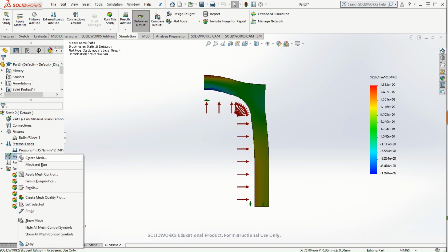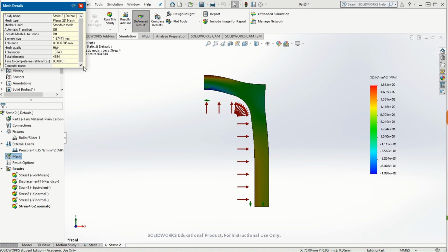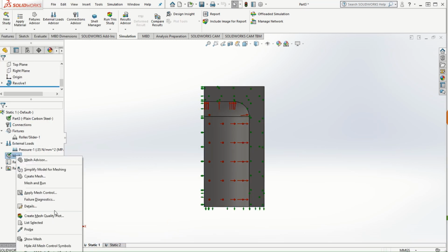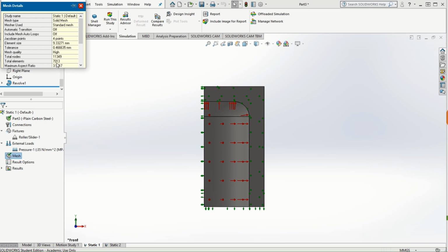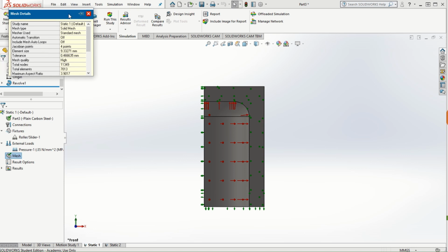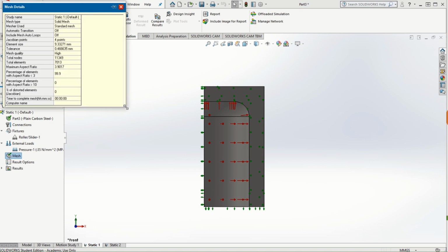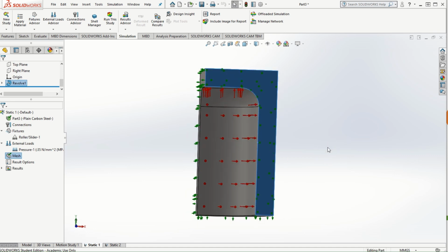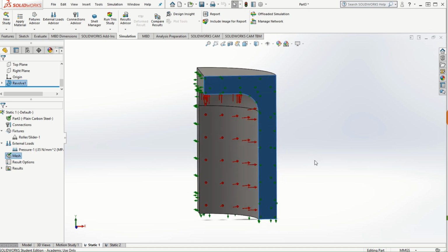If you look at the mesh statistics, here we are using close to 5,000 elements and 10,000 nodes, and for the solid model we used 7,000 elements and 11,000 nodes. So it's not a really large saving in terms of the mesh size, but again there is at least some advantage of dealing with the simpler geometry, so that you still get accurate results as compared to the three-dimensional or a two-dimensional model to validate with the theoretical values.